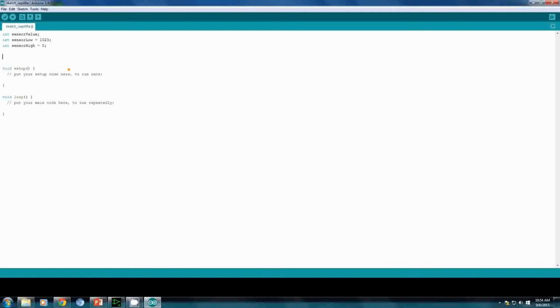So now let's create a constant, and it's an integer type, and we do LED pin. Okay, so now notice that in our circuit and the components that we're using, we didn't have an LED as one of our components. The reason being is that there is already an LED attached to the Arduino board, and internally, the way this board is set up or built, it is connected to pin 13.